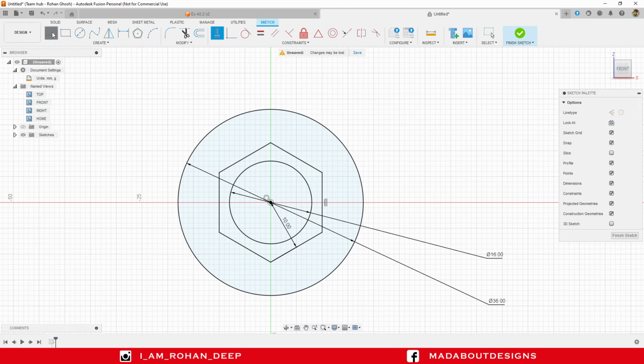Go to straight line. Turn on the construction feature and draw a vertical line from the origin as follows. Give it any length, it won't matter.